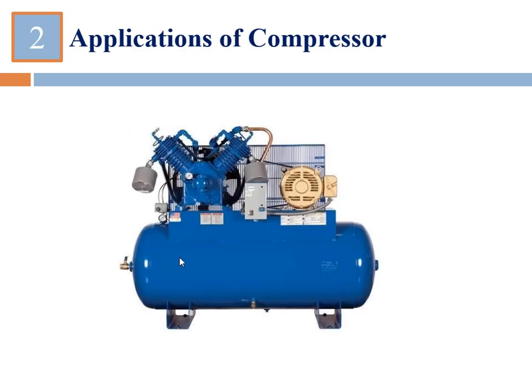You might have seen at an air station or in the service stations of vehicles this kind of device. This blue color tank is nothing but the receiver tank, which stores the high pressure air. The delivery side of the compressor is connected to this end, and then the high pressure air is stored here.